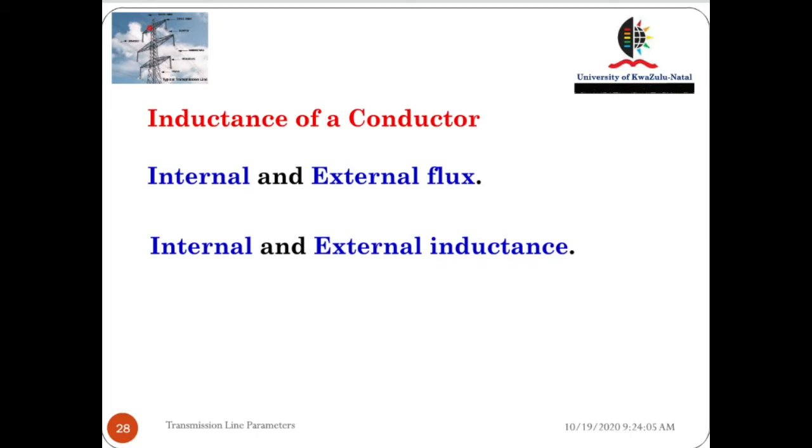High ampere, the radius of the conductor is R and is placed in the air, and it's a solid conductor, round, cross-sectional area is circular, and it's a very, very long, like infinitely long, conductor. The reason why we are assuming an infinitely long conductor is that we want to make sure that it complies with all the requirements to derive the formula for flux, and hence the inductance value of the conductor due to that current.